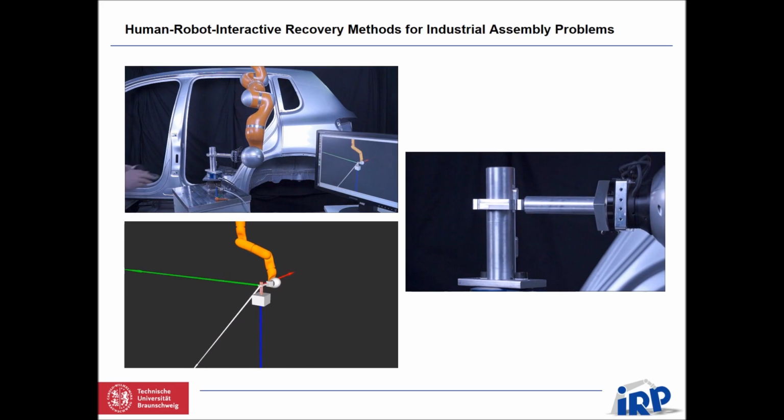The video on the right shows a close-up of the first assembly problem, which is triggered by a tilted conrod. As the Cartesian impedance controller was not able to cover this problem, the resulting forces gained and the process stopped. In this case, the top assembly problem is exemplary solved using the space mouse.